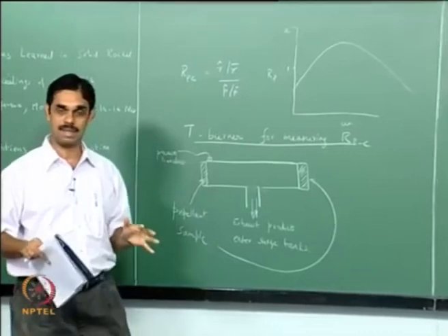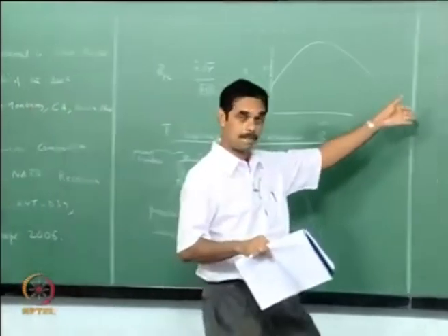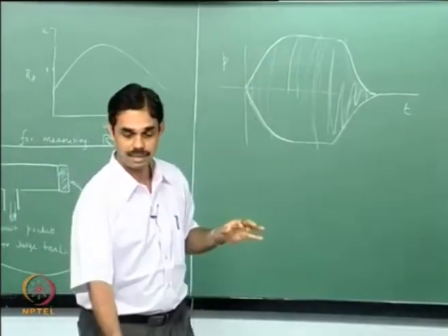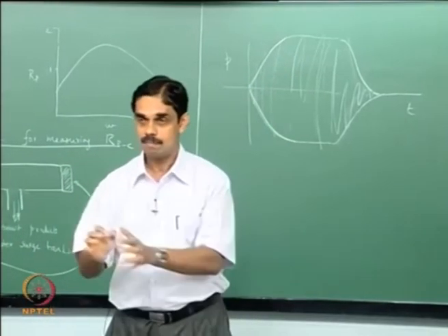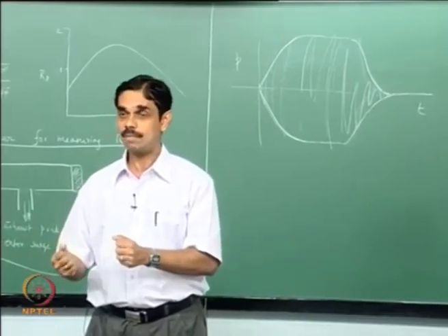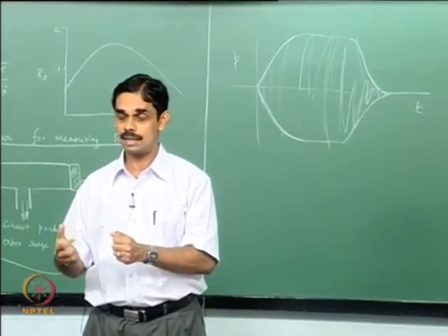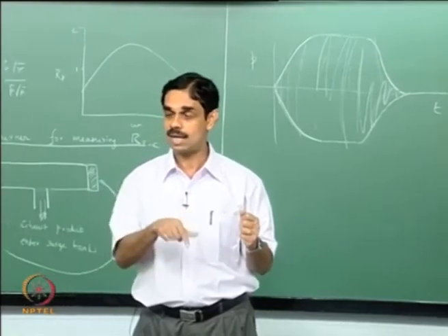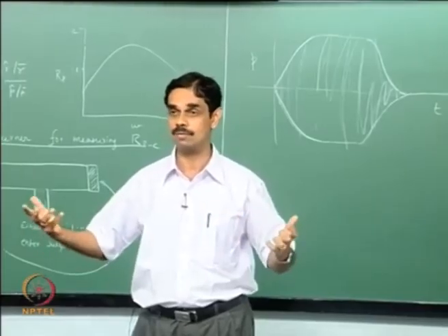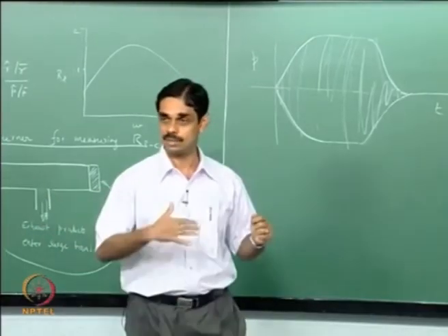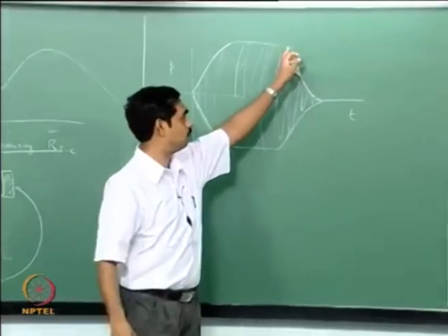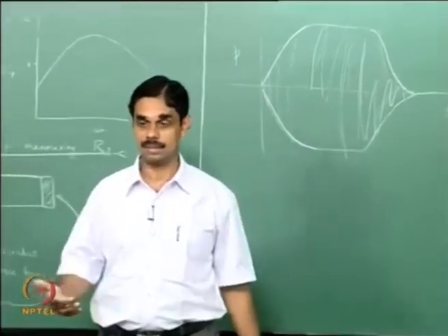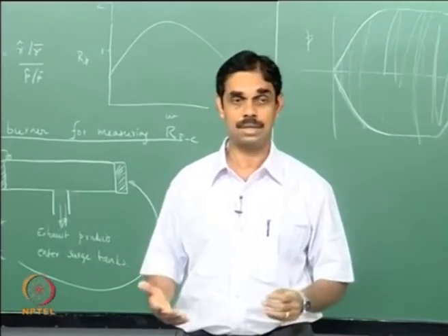So that is the crux of the matter: you have growth, but when it grows there is not only propellant driving. Let us say there is a certain alpha 1 quantity of driving minus alpha 2, which is the losses, but you have to measure the alpha 2, and what you are measuring is alpha 1 minus alpha 2. Suppose you know alpha 2, that can be added to alpha 1 minus alpha 2 to give alpha 1, and the way you find alpha 2, the decay, is by looking at the slope of this curve once the combustion is complete, and from that you can get the decay rate. So I hope this is clear.